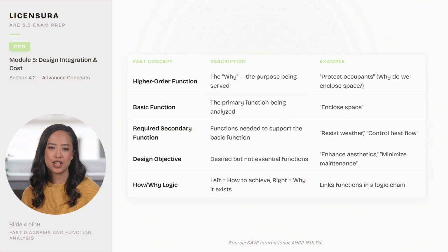This list covers Value Engineering Change Proposals, VECPs, which occur during construction. The contractor proposes alternatives and savings are typically shared between owner and contractor, often on a 50-50 basis. The architect must review every VECP for compliance with design intent, code requirements, and performance standards. VECPs cannot reduce the functional requirements of the contract. Federal projects often require VECP provisions in their contracts.